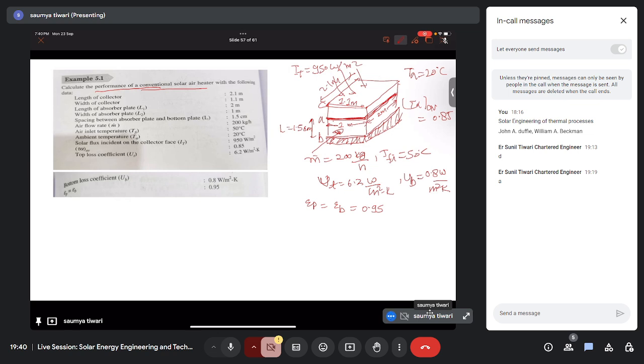So what we will calculate is the heat transfer coefficient for the fluid, for your plate and your back plate. Your inlet fluid temperature is 50 degrees Celsius. Assuming that your average or mean temperature is 55 degrees Celsius, because you need to calculate all the dimensionless numbers, you need to have some mean temperature on which you will calculate the parameters for your air, right?